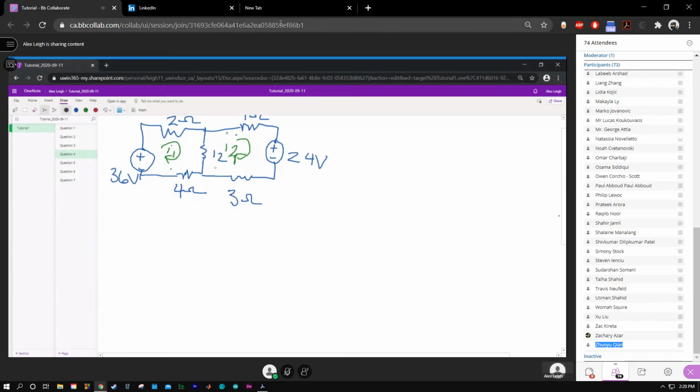So you have to, well, I don't know that you have to. I usually do define the currents going in the same direction. I just like to be consistent with how I do them. I don't know if it's a rule or not. I wouldn't call it a rule, but generally I do. Again, I'm not 100% sure on that, but I always have. So define them in the same direction just to keep yourself consistent. In my case, I usually like to go clockwise. You can go counterclockwise. It shouldn't matter as long as you are consistent with your current directions. That is the most important point.